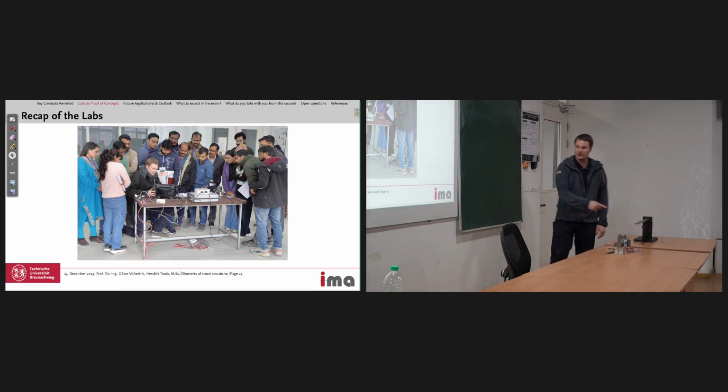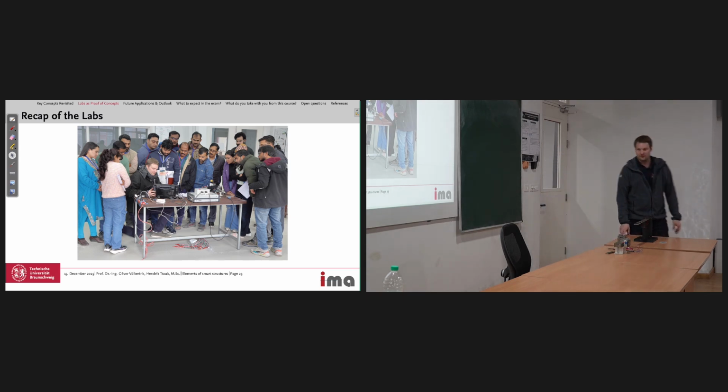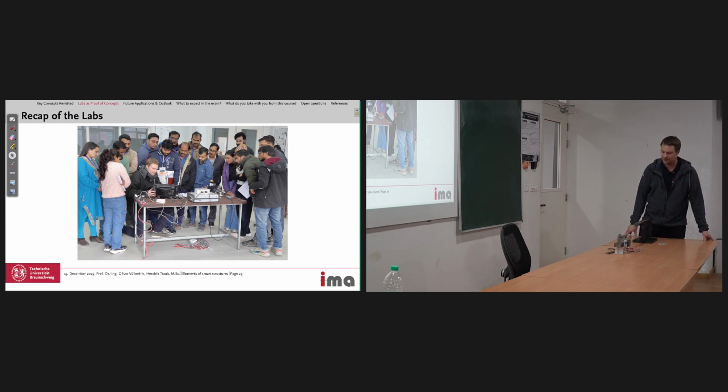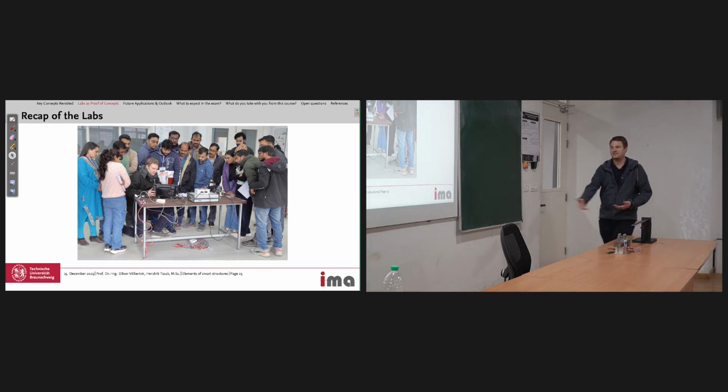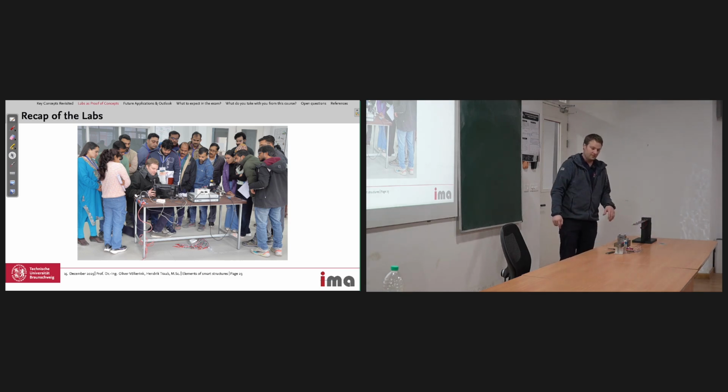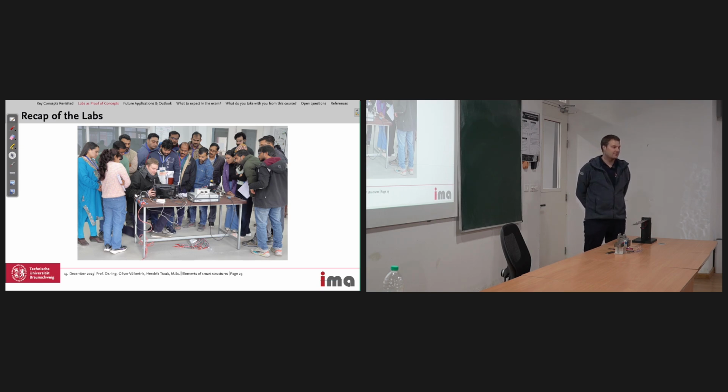we used two tables, completely separated, and then the signal got much, much better. So you really have to look for the surroundings. Also, the tables in the lab were wood, so we expect some vibrations, and you realize as soon as somebody steps on the ground or touches the table, everything shifts a little bit. So be careful with your whole setup, that it's as isolated as possible against vibrations. Okay, that was the fourth experiment.